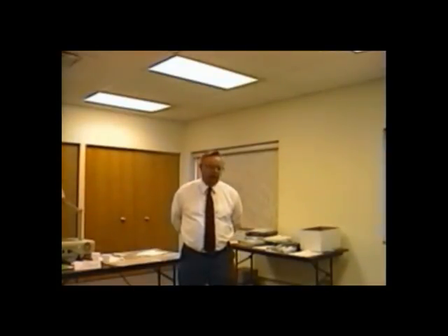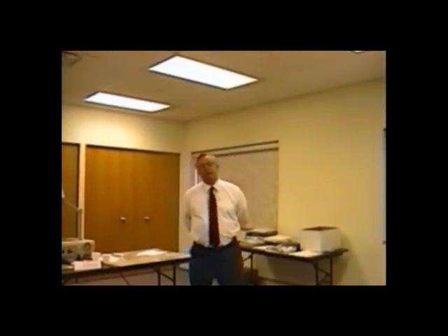We're going to be talking about undercharging systems and overcharging systems and properly charging systems. Just so you understand that in this class we're going to be talking about residential AC and fixed orifices. We know that we have capillary tubes as a metering device, fixed orifices, and expansion valves, thermostatic expansion valves. When you have a capillary tube or a fixed orifice, we want you to understand that the charge is very critical. And we would say it's plus or minus how many ounces.